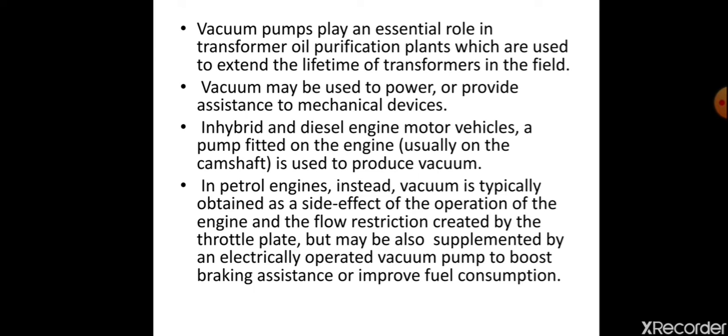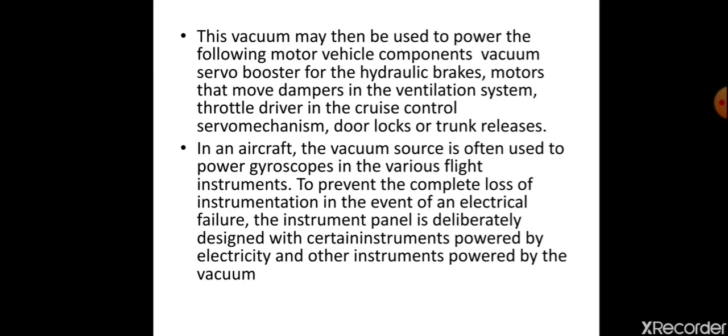In hybrid and diesel engine motor vehicles, a pump fitted on the engine, usually on the camshaft, is used to produce vacuum. In petrol engines, vacuum is typically obtained as a side effect of the operation of the engine and the flow restriction created by the throttle plate, but may also be supplemented by an electrically operated vacuum pump to boost braking assistance or improve fuel consumption.